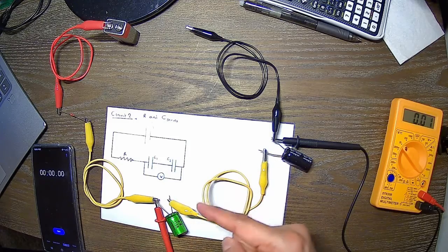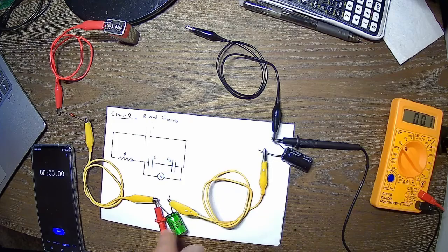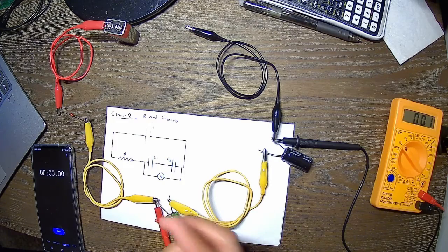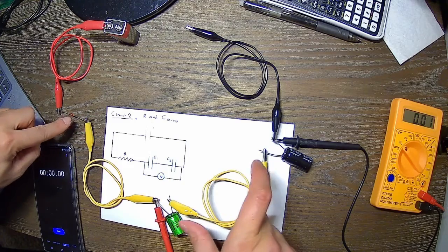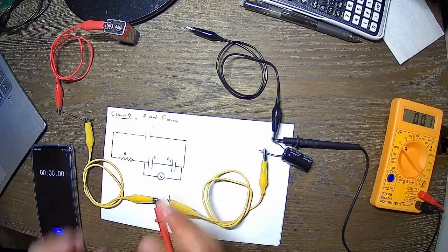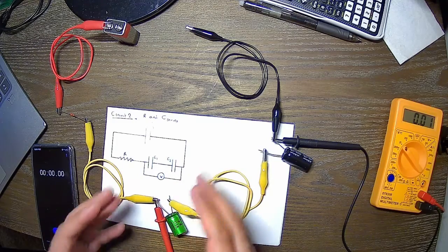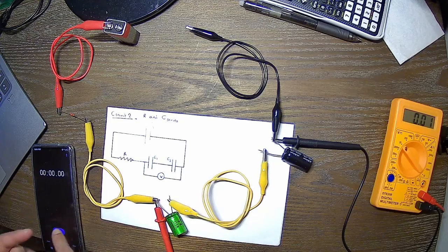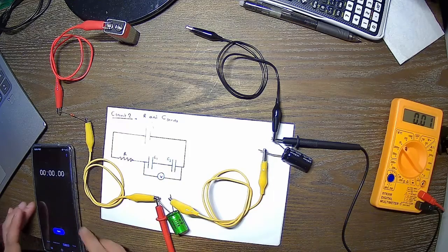If you take the inverse, then the C series is going to be smaller than the lower one, correct? So with the same R but a smaller effective C value, the time it will take to get to the 63%, the 6 volts, is going to be shorter than it will take for the smaller capacitor. Okay? Let's see if it indeed is true.